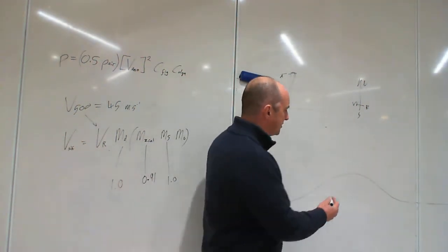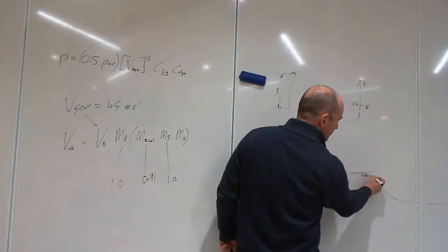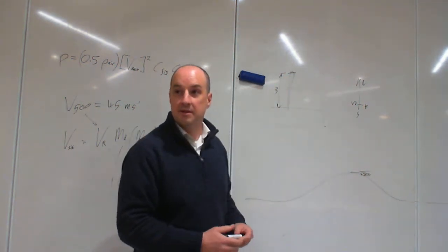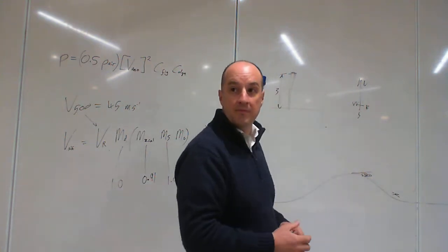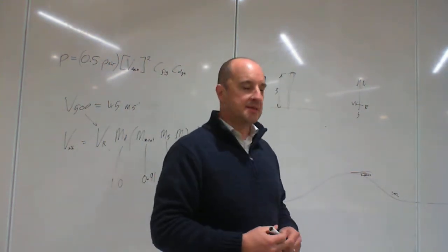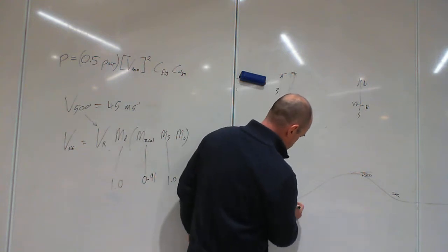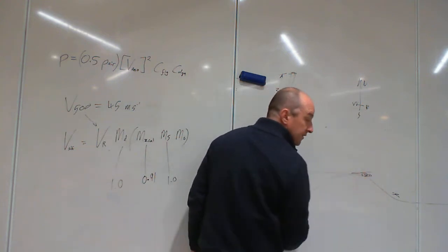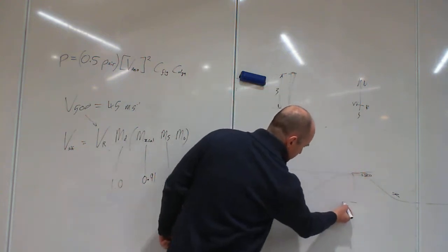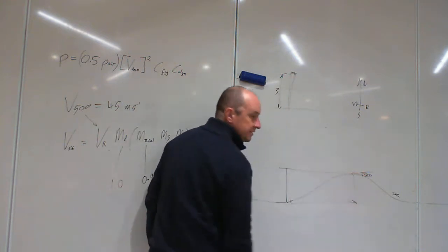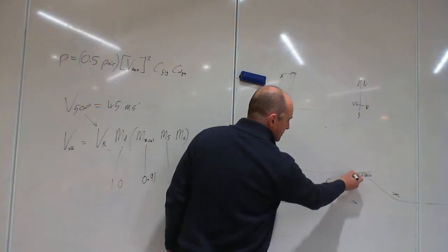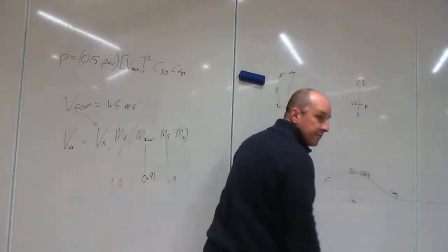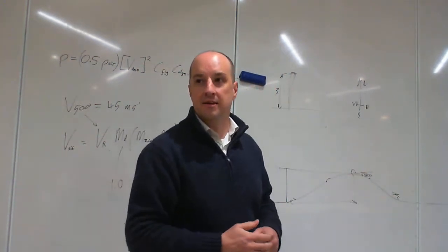In a steeper hill, you also get a separation area here, where you get some sort of turbulence. Okay? And finally, if you're down here, you've actually got shielding for that hill. And so the topographic multiplier says, what is the height of that hill? What is the length to the height there? Where is your structure? Is it down here? Is it here? Is it right on top? Is it back here? Is it back here? And gives you a factor for that.